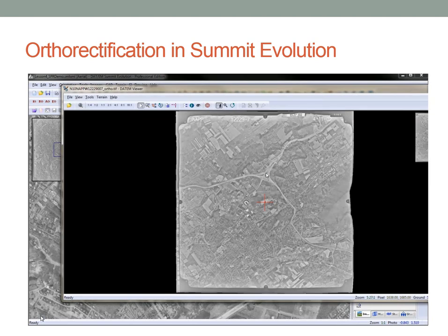Okay, and you can see that there's definitely been some terrain correction, particularly on the right-hand side of the image over Mount Nittany. The image has actually been resampled and pixels have been moved horizontally to account for relief displacement.